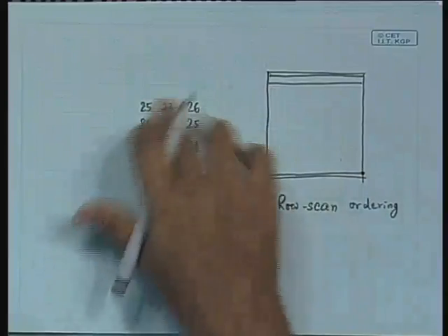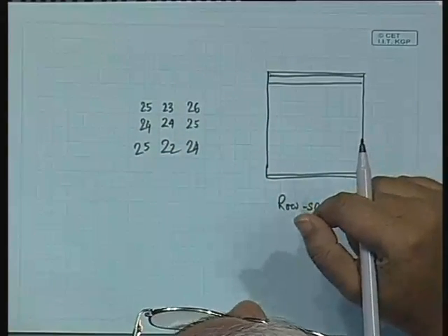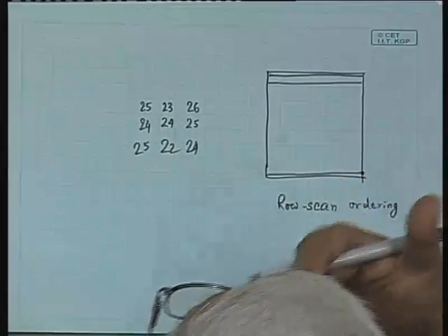Why? Because whenever we are getting the image samples, even if we do not quantize these samples, still we can reduce the number of bits, by sending just the first one, and then encoding the rest by differential pulse code modulation. In that case what you are required to send is only the incremental information, which is going to take much fewer bits as compared to encoding individual pixels, because the entropy of the differential signal is much less as compared to the entropy of the original signal. So, it will require far fewer bits to encode, and we will be able to achieve compression, and that compression is lossless because we need not truncate those values.